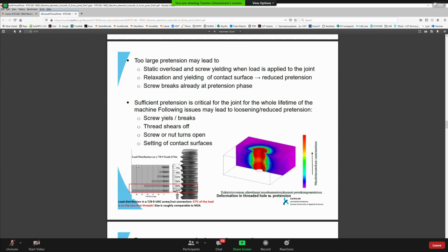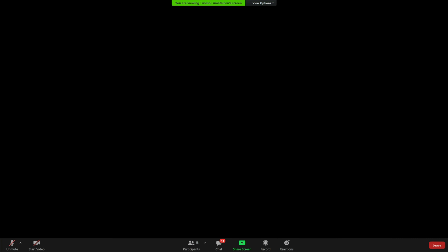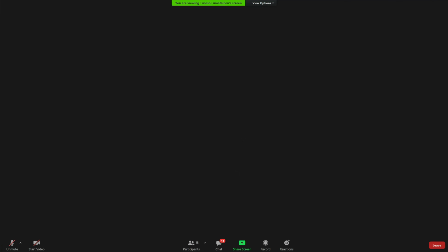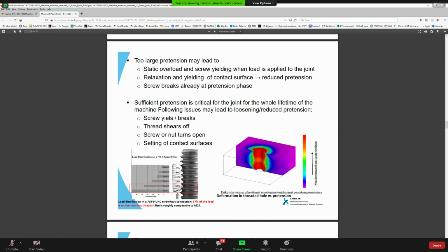So also, one of the ways of breakage of the bolt is that if you have too large a pretension, you can break the bolt by that. You can overload the screw so that it will instantly snap. That has happened. So then you know that you tightened too much when you hear the snap, and then there's no more counter torque, and then it's a whoops again.